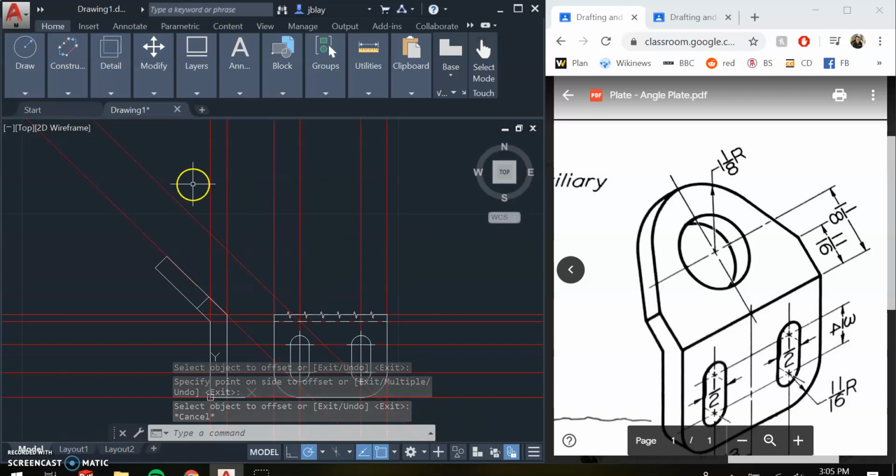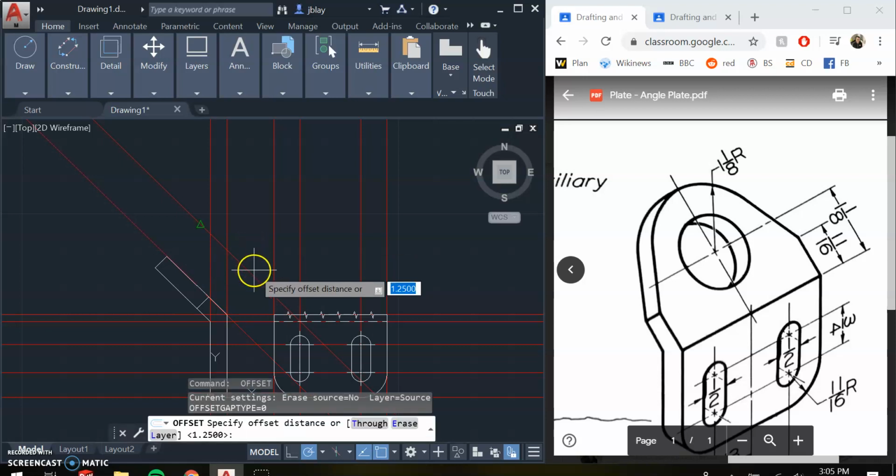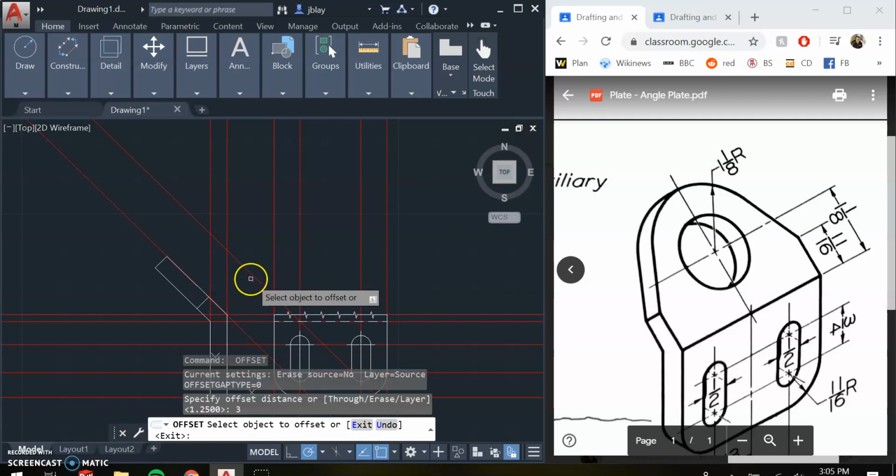Sometimes if you have a top view as well, you don't leave out one of the views. You want to space out the auxiliary view more. It really depends on the situation, but you could just use 1.25 as your default distance, but when it doesn't fit or you don't think it'll fit, use something else. And then I'm going to offset this again by our depth, which if we remember from the last video is 3 inches.